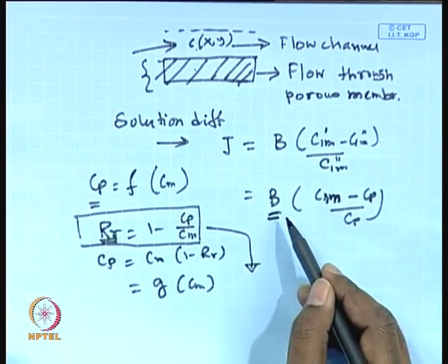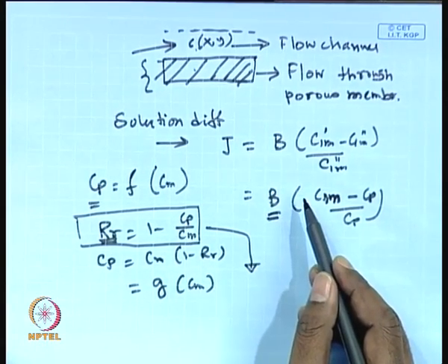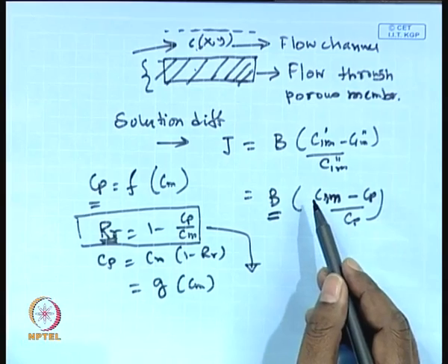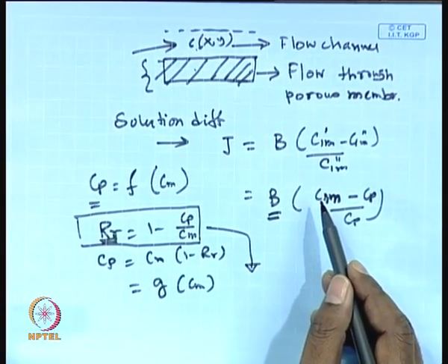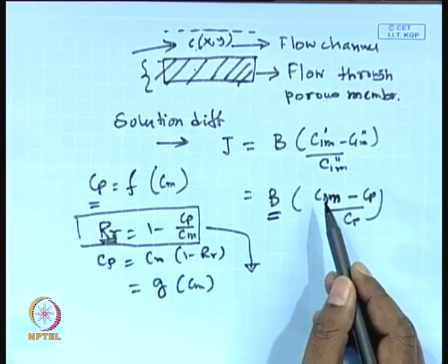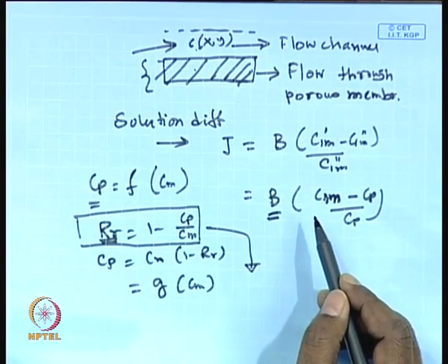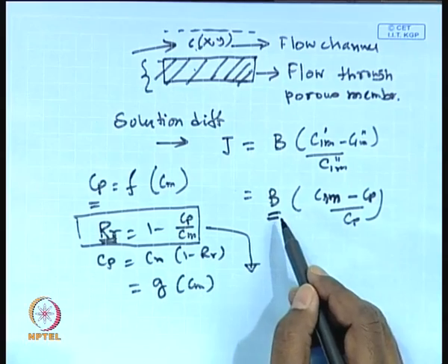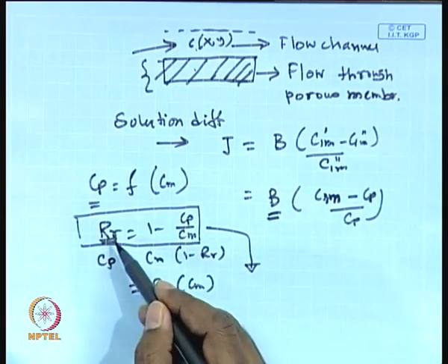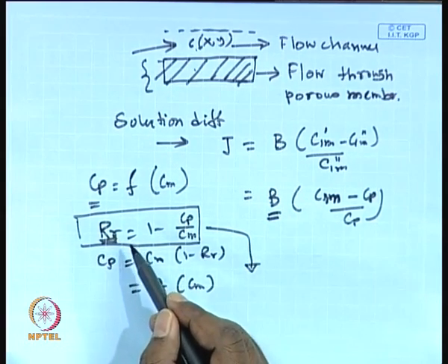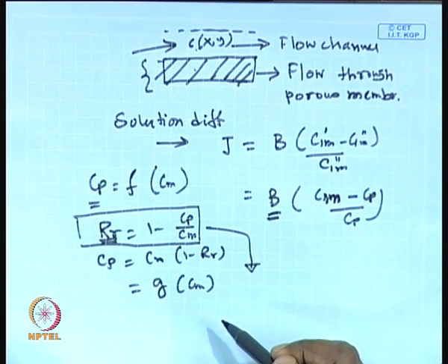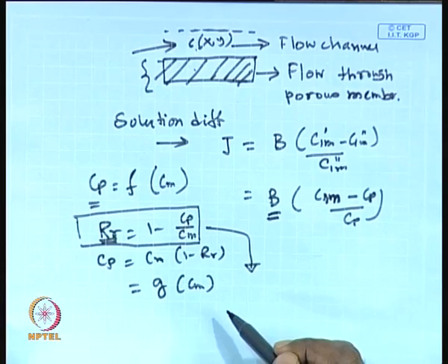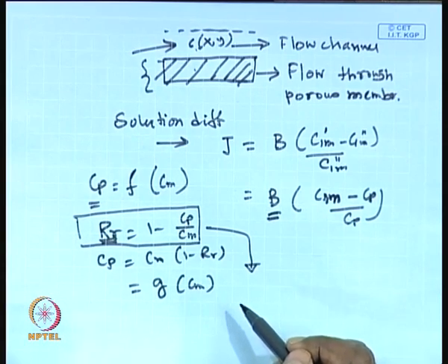On the other hand, it creates a complication or an inaccuracy during the modeling or calculation stage, because for half of the data you have to use the experimental values to determine the value of B. On the other hand, you can use the real retention formulation for completely predictive calculations. Okay, that is the difference between the solution diffusion model and the real retention formulation.